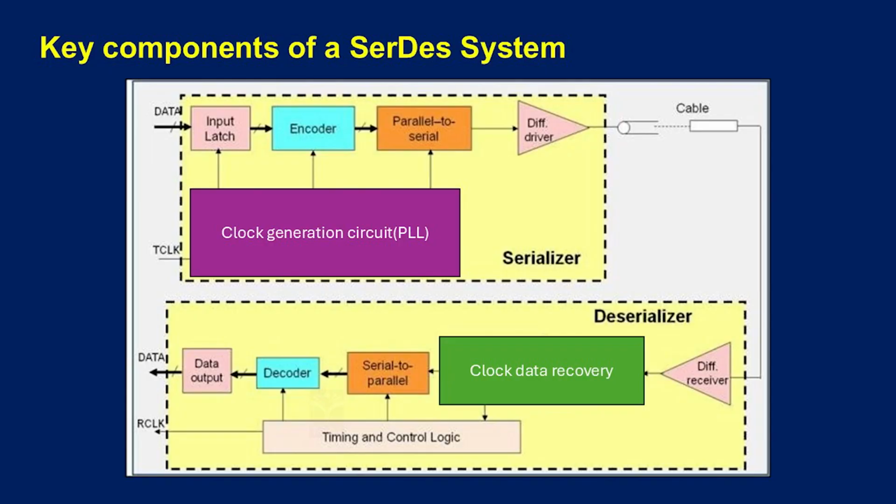Okay, so key components of a Serdes system, as I said, are the input latch, encoder, parallel to serial, and differential driver, right? The differential driver means the output is differential here. It is a single data, it can be a CMOS data. Input latch, encoder, all of these blocks are working on a PLL.